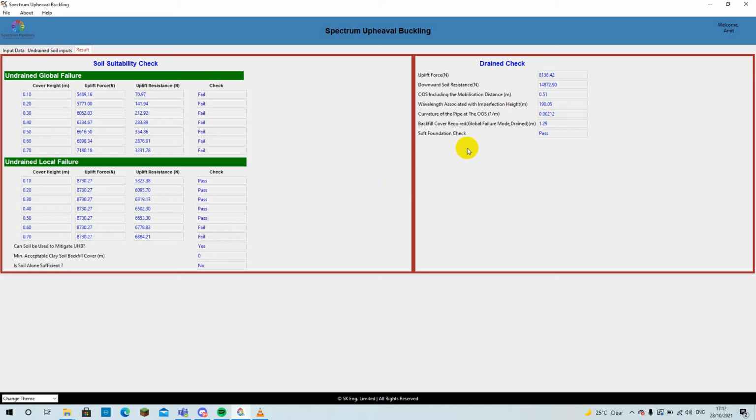If the soil is not suitable for upheaval buckling mitigation, then the soil needs to be dredged out of the trench, and rock needs to be placed directly on top of the pipe. In such scenarios, some residual locally failed clay slurry may remain in the trench. The depth of the slurry layer is considered in the calculations for the required trench and rock cover height.